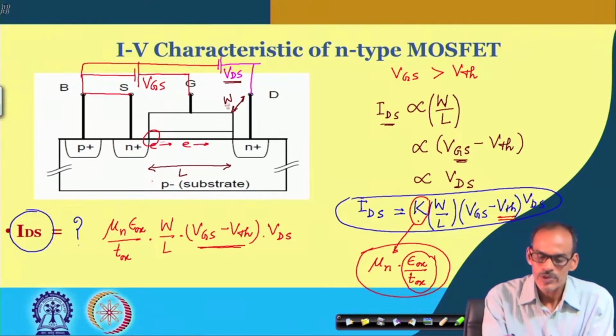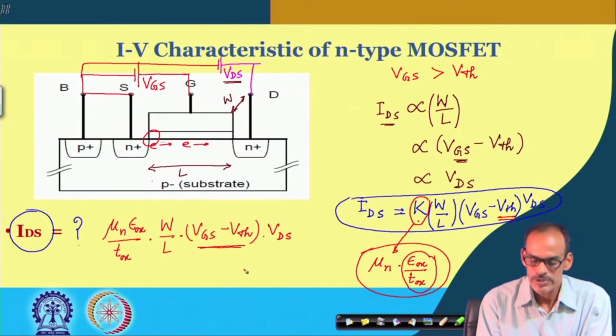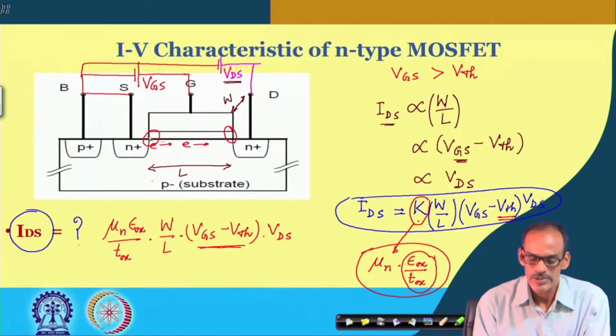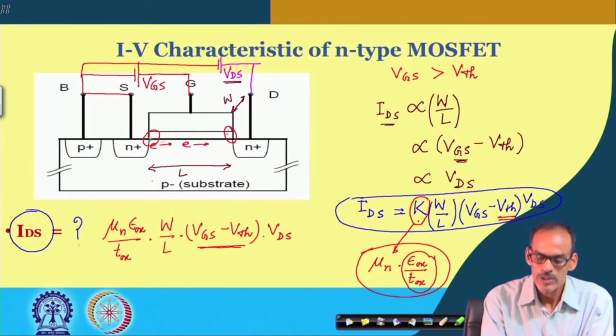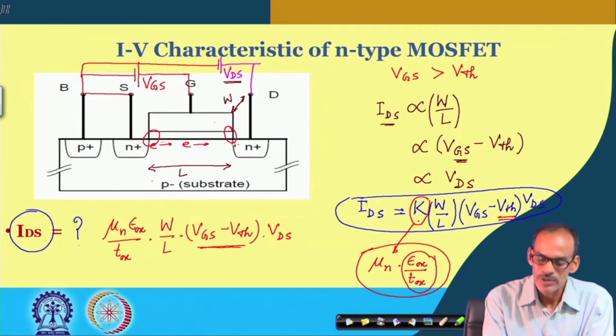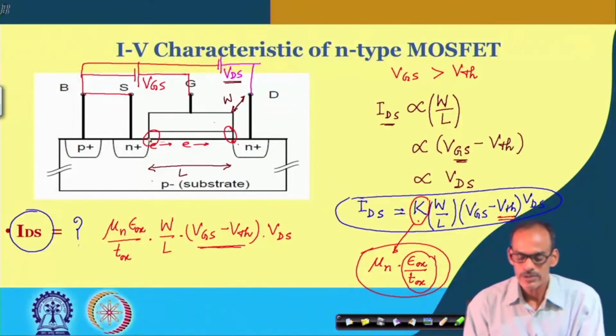Then if I consider we are applying a voltage VDS, which is positive, that means the voltage across the structure is not the same as the VGS here. In fact, that is supposed to be VGD, which is VGS minus VDS. So, naturally the conductivity of the channel towards the drain side and the source side are different.